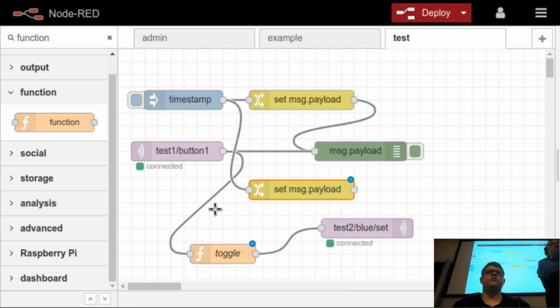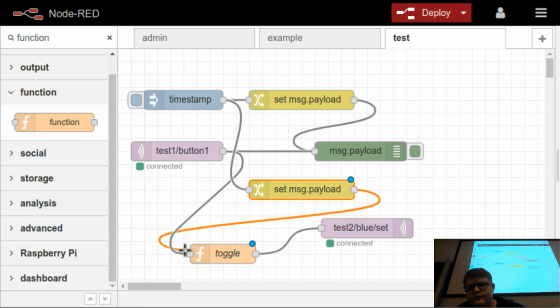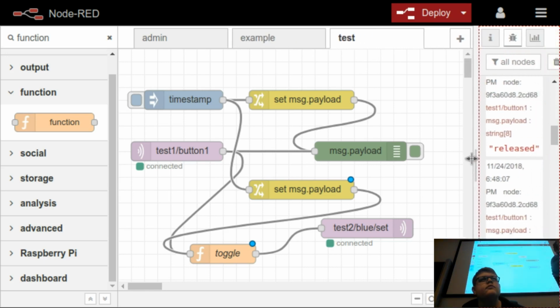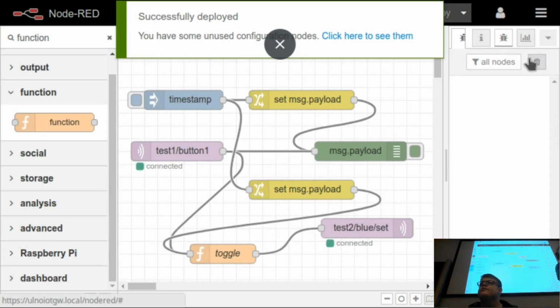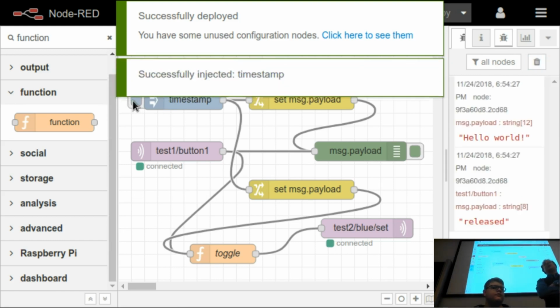What can happen? You see here that we also get some other messages in between. You see there are lots of released messages coming in between, even if we don't press the button here. So what do we need to do to prevent that? Maybe some debouncing of the key? You're thinking in the right direction, but it's even easier than debouncing.